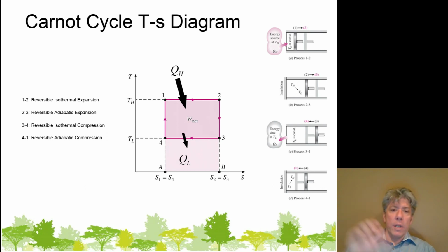And so if we want to put heat in to get some work out, we have to accept the fact that some entropy is going to come along with it. And to get the system back to where it started, in other words, to operate it on a cycle, we will have to transfer heat out and thereby get rid of that extra entropy of the system. Now, one interesting thing about this is that the net amount of work produced by the cycle will be the difference between the heat flows. We knew that from before, or by an energy balance around the cycle.